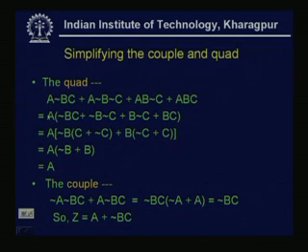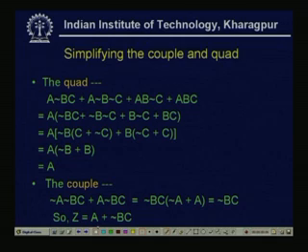From here, we notice that each of the min terms contains the literal A. So, I take A common, then the term will be A times B bar C, B bar C bar, B C bar, B C. Now, from the inner expression, if we consider the first 2 min terms, then B bar is common, and then we take C plus C bar.